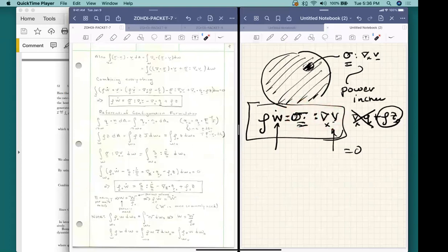And of course, we've seen it in medieval movies where we have some kind of metalsmith sitting there with a hammer, mashing on an anvil and making a sword, and the thing is getting hot, and then they take the sword and dip it into ox blood. And of course you wonder, well, was it hot because the person took it out of the furnace and heated it up? It would have been hot even if the person was banging on it with a sledgehammer with no heat. Of course, heat helps make the material more pliable, but just the stress alone from the impact of the hammer will increase the temperature of this dramatically.